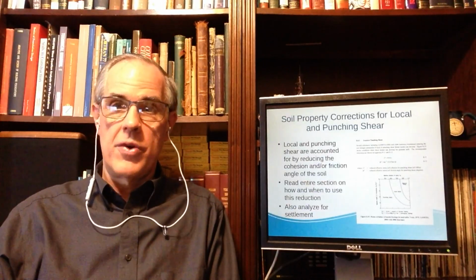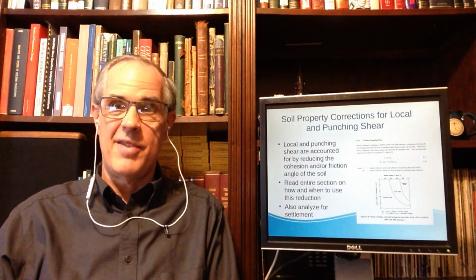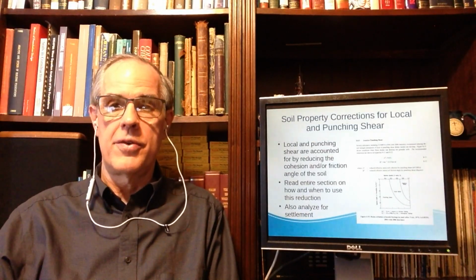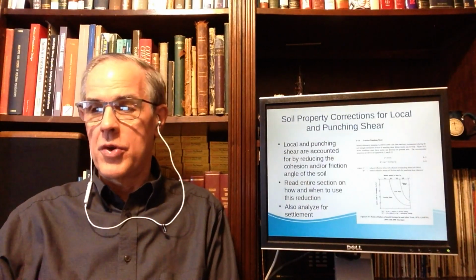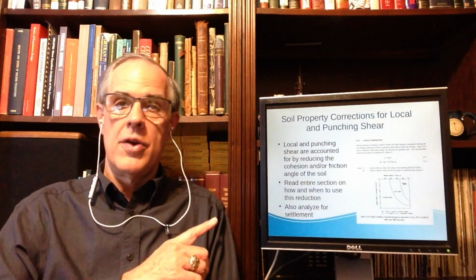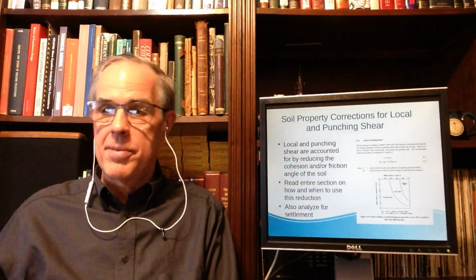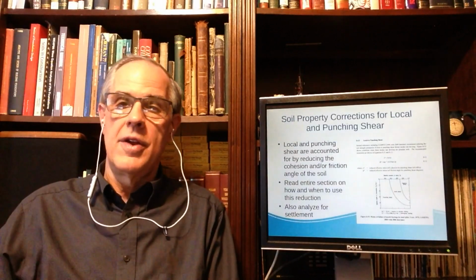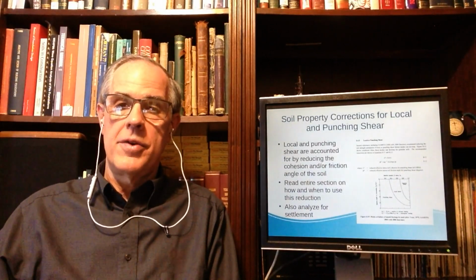And of course, analysis for settlement is mandatory for any soil, but particularly for softer soils. Look at this chart where you have regions of general shear, local shear, and punching shear, and the reduction factors. You need to read those carefully when you're applying them to your problems.